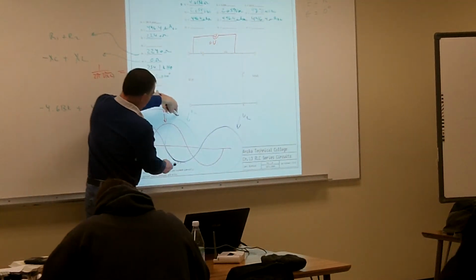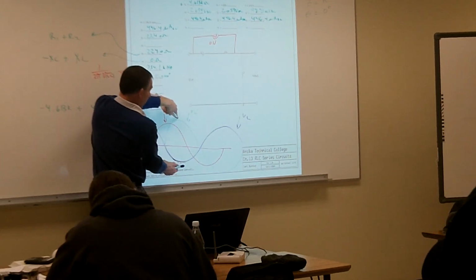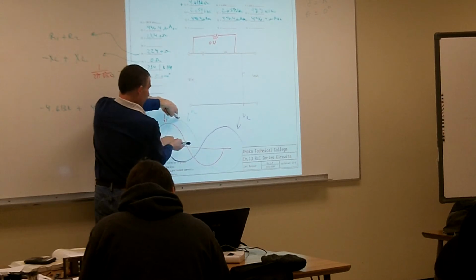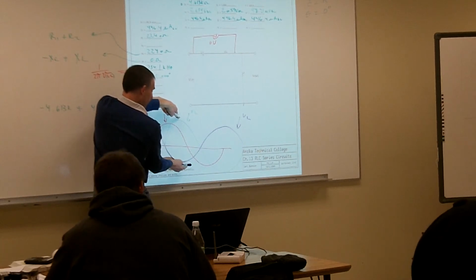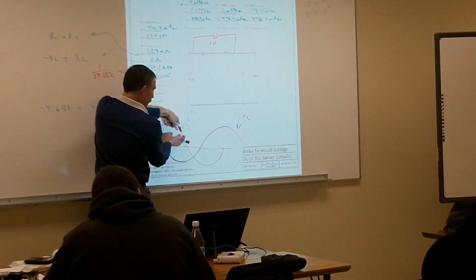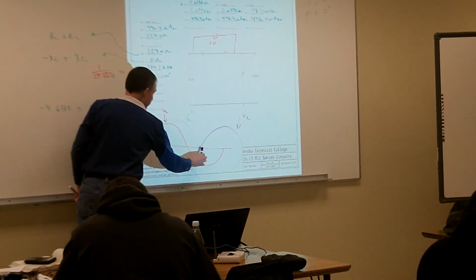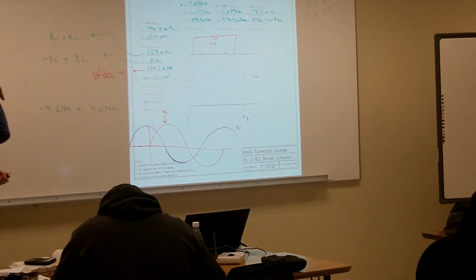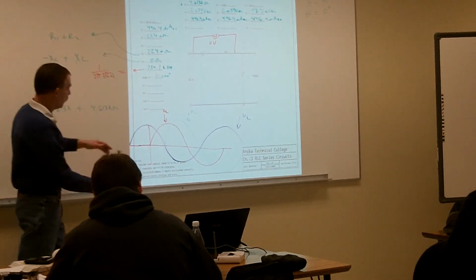So if I'm measuring, I've got a voltage across the capacitor of 2.059 volts AC, and that's positive at that time. Then my inductor is actually series opposing that voltage, and it's going negative at that time. So those two cancel each other out, and that's where I end up getting 0 volts, because of the phase angles of each one of these. Because VC is going up when VL is going down, they're opposing each other's voltage, and those two are going to cancel each other out.